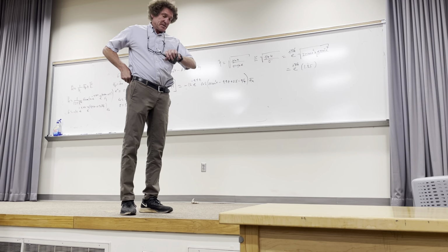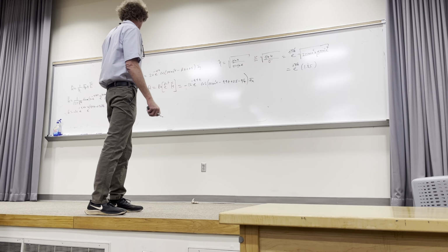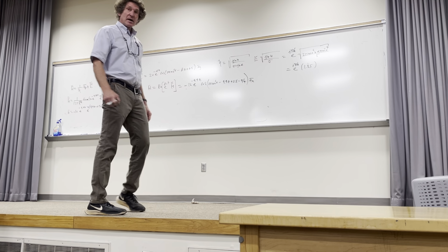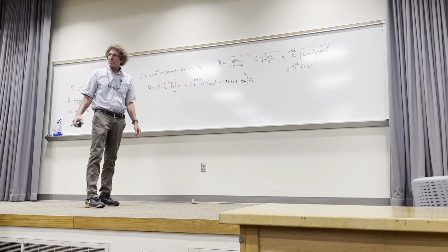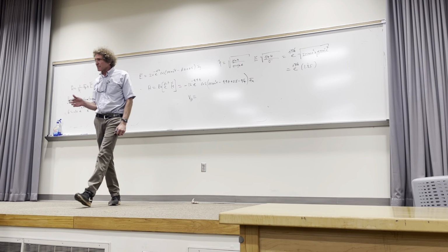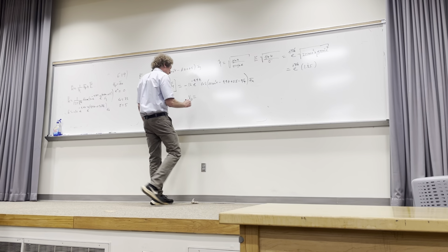Sometimes it's not a really good conductor, so you have to use both sigma and j omega. All right. So that problem showcased everything you need to know. By the way, if I asked you for the velocity of propagation, the phase velocity, what would it be? What's the fundamental definition of phase velocity? Omega over beta, right. So what would it be in our case?